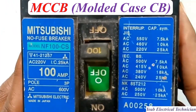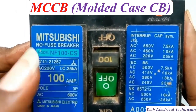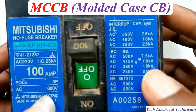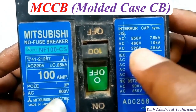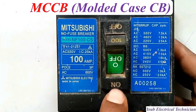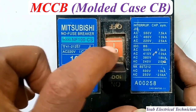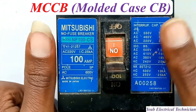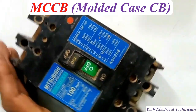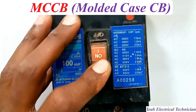Its name came from the insulating molded case that houses its internal components, and it's used for high current ratings and large electrical systems such as those found in industrial and commercial buildings. MCCBs protect electrical circuits, cables, and loads from damage caused by overcurrents, such as those from overloads or short circuits. They are used in applications that exceed the limit of smaller circuit breakers like MCBs and can handle a wide range of voltages and currents up to 2500 amperes or more.